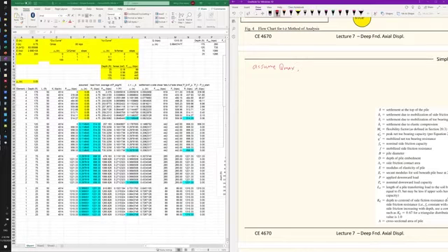So that is the maximum toe bearing capacity at the toe, and after we have the Q max and also the F max, the maximum side friction, you can evaluate those, actually the Q max and F max, just like lecture number 5. If you evaluate the pile capacity using the alpha method or beta method, then you can find out the side friction capacity and also the toe bearing capacity for the pile.